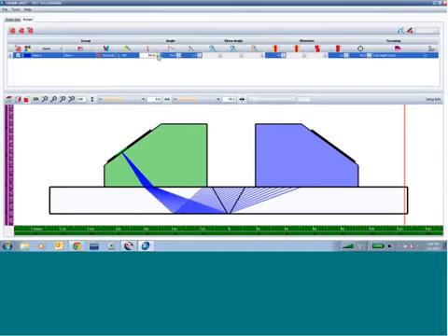One thing that I can do is add or remove angles from the beam set to interrogate the rest of the area. I want, as best as I can, to cover the heat affected zone at the OD and the ID with those specific angles, somewhere between 35 and 58. So with this position, I would be covered quite well at the top, but maybe not so well at the bottom with the angles that I want.